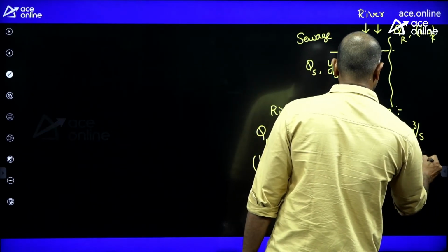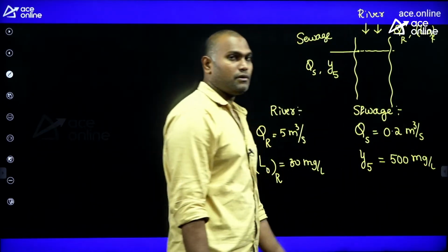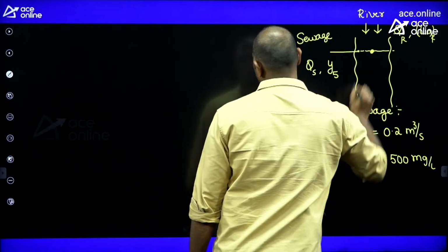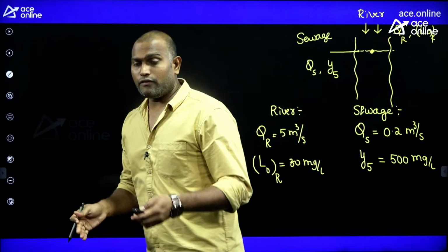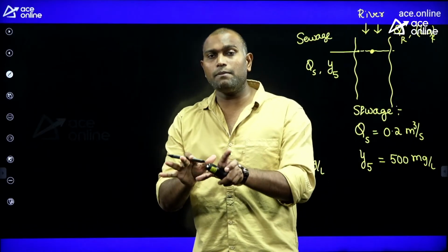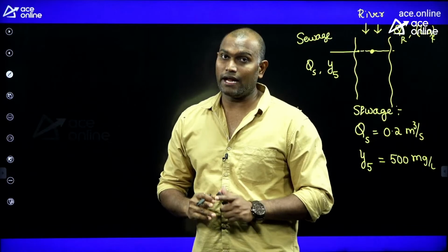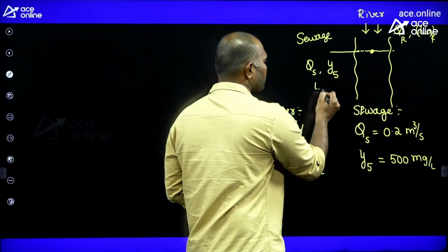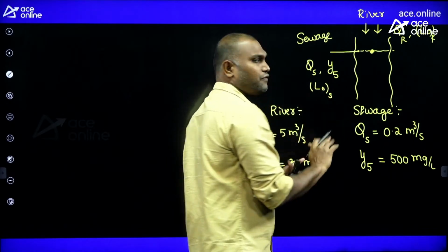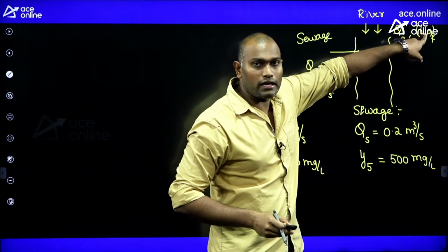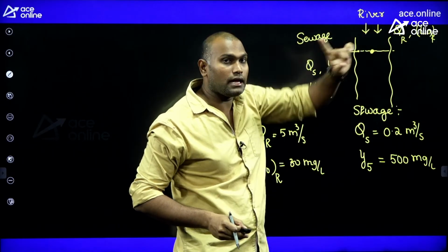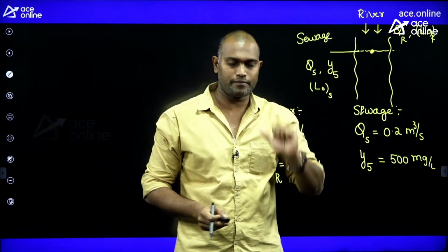Mind you, this is not ultimate BOD, that's a 5-day BOD. And they have mixed instantaneously. So when they mix, the ultimate BOD of the mixture will be different, right? So it has a different ultimate BOD, L naught of S. After mixing, immediately the ultimate BOD changes, right?